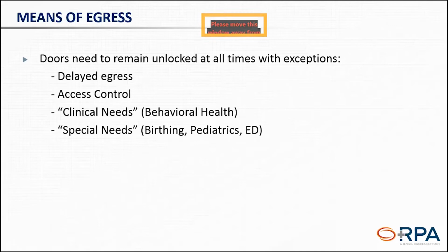device. So if you looked at the allowances for access control in chapter 7 of NFPA 101, you can see that there's a laundry list of items that are required when we do have access control. Namely, do we have a motion detector that'll release the magnet upon approach? Is there a release button within 5 feet of the opening that says push to exit? That's kind of the backup to the motion detector. Does the magnet release on fire alarm? Does it release on loss of power? Do we have emergency power, emergency lighting on the egress side of that access control? There's a big long list of things that we have to have with those types of devices. So make sure you have all of those pieces parts.